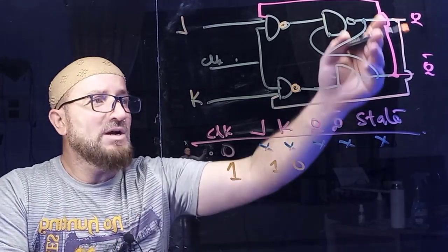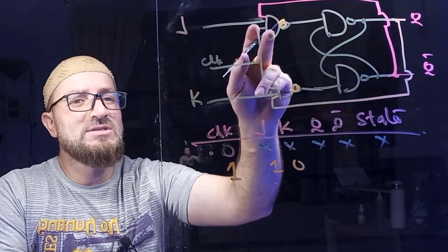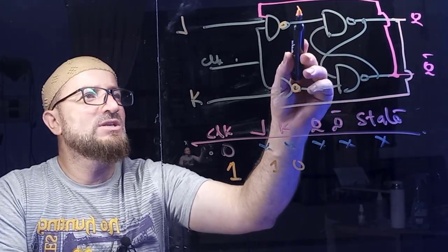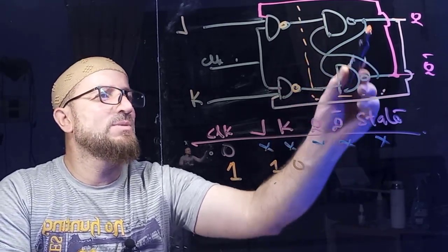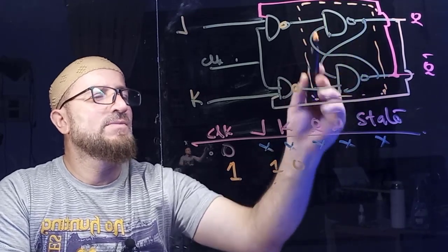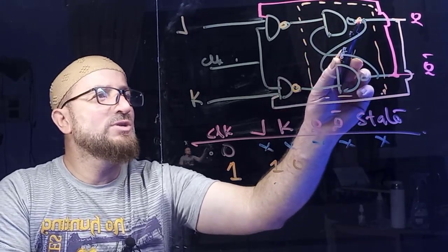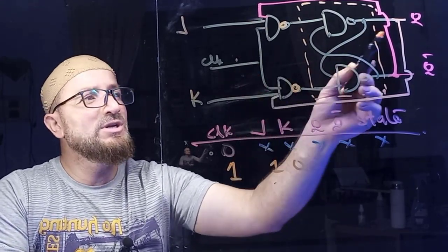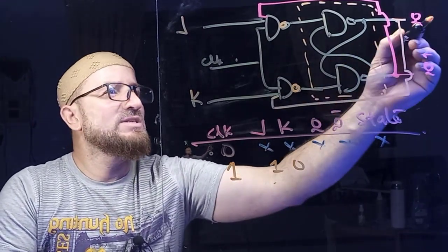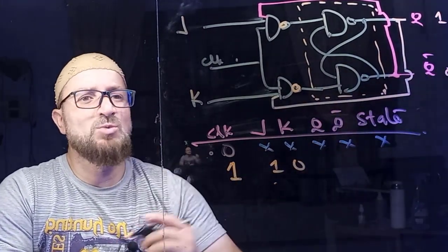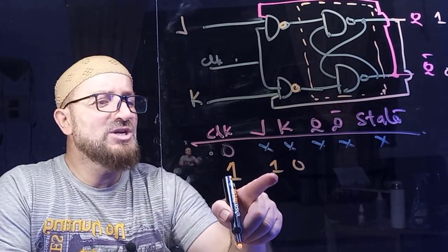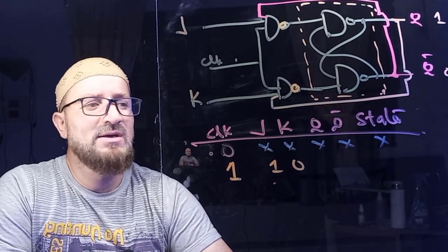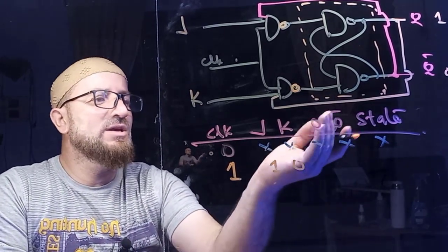because of the additional feedback into this latch, which was internal. This is our basic latch, the dashed one. Before the inputs, we also need to see what was the previous output. Here, to this NAND gate, we also need to see what the previous output was. Say for example, it was a set state, that is 1 0. And I'm putting J1 and K0. Okay? And I have to see what will be the Q and Q complement.